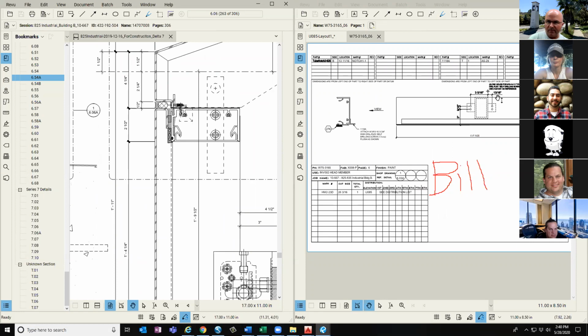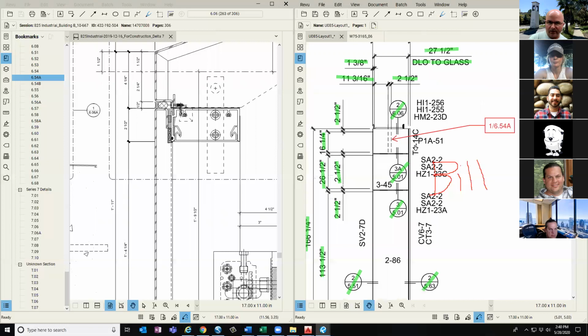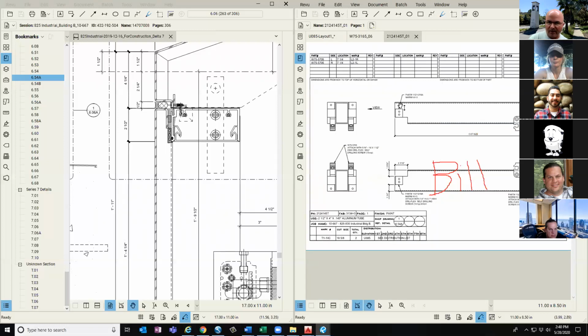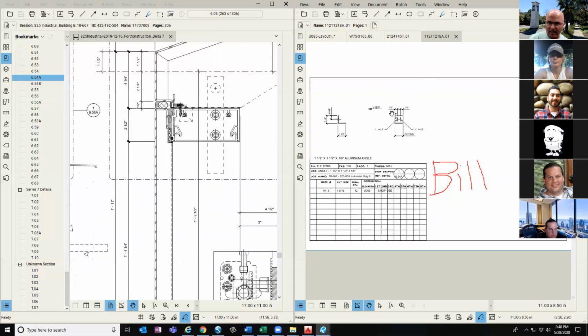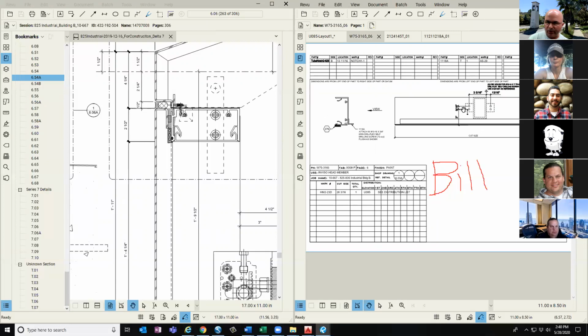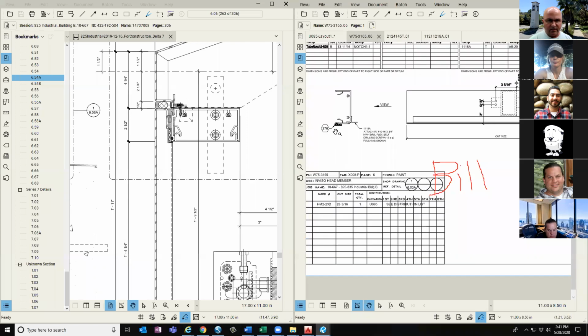Dimensionally, it's going to be the same, but I have a smaller clip because now that clip has to actually fit on the other side of this screw port, which is why you saw when we looked at this tube, it had a notch up at the top and it's got a much shorter angle. So we'll look at that angle, see what the spacing is, verify that on my horizontal part, make sure that these all match, because we're going to put pilot holes on there when the shop goes to assemble these. They're just going to run the screws in under the pilot holes and they've got the tube positioned where they need it. I'm seeing that there's a gasket 276.